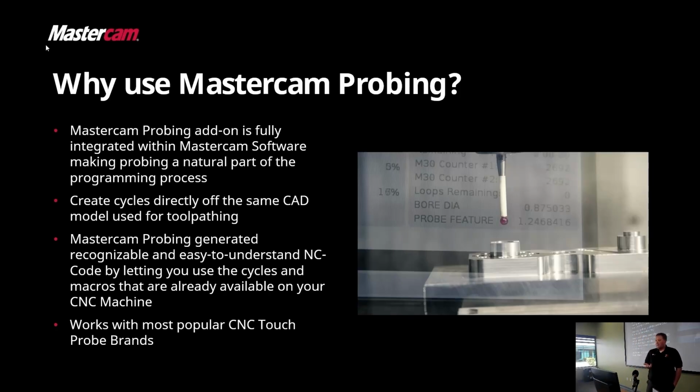Mastercam probing does use, we'll pick on Renishaw for instance because they're quite popular here in the States, the Inspection Plus macros. Those are the standard 9800 series macros that, if you are using a probe, either through something like a VPS or by hand, you'd recognize and be familiar with. And of course we support more than just Renishaw, whether that be Blum, Marposs, a ton of different options, along with custom cycles that can definitely be built out using the core technology.